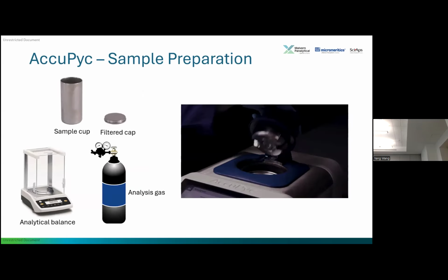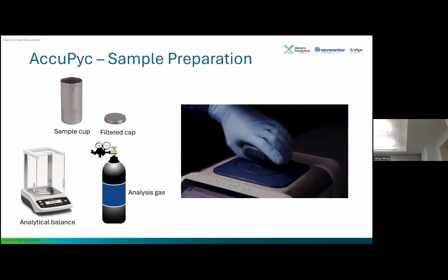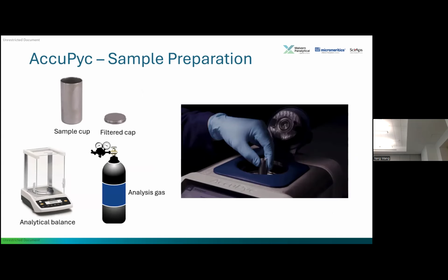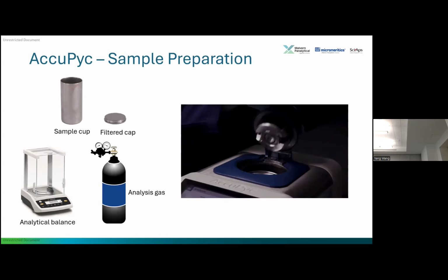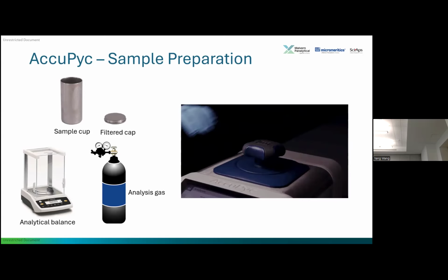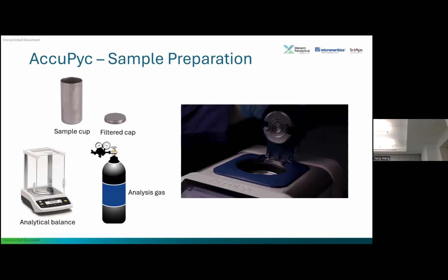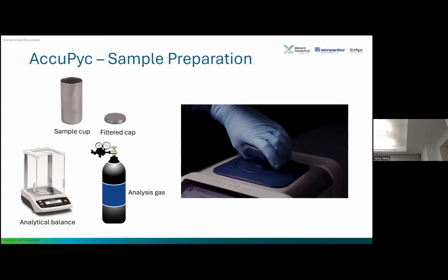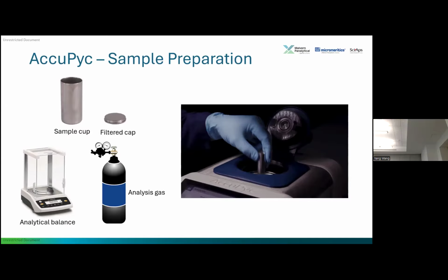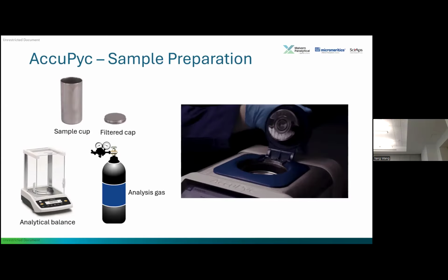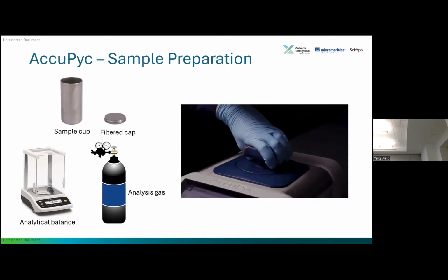That's just an image of the instrument. I open and close it to load a sample. There's very little sample preparation. If you do have samples that have some moisture on them, you might want to dry them before you put them in the instrument, because if it dries inside the instrument, you can have changes in volume, like a trend where the volume is decreasing because water from the surface is coming off.